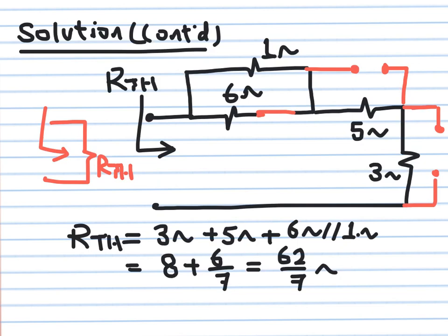And I'm warning you again one more time, do not touch any dependent sources. Dependent sources do not represent actual sources. They represent circuit components, they represent transistors, they represent op amps, they represent amplifiers. So you should not remove them, they are part of your circuit.